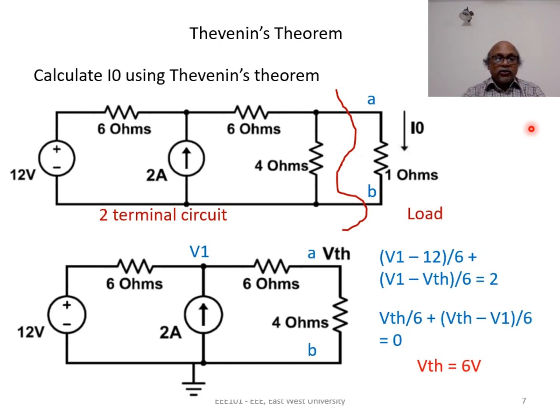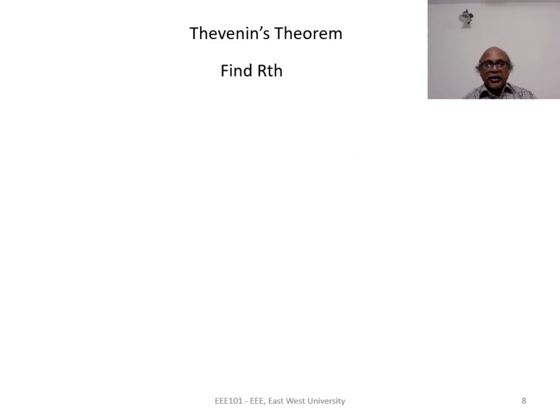Usually, you don't need to apply multiple techniques to determine RTH, but to test our knowledge of RTH calculation, we will calculate RTH of this circuit using all three techniques and then we will verify if we get the same result. Okay. First, we consider case 1. In case 1, we deactivate the independent sources and find REQ.